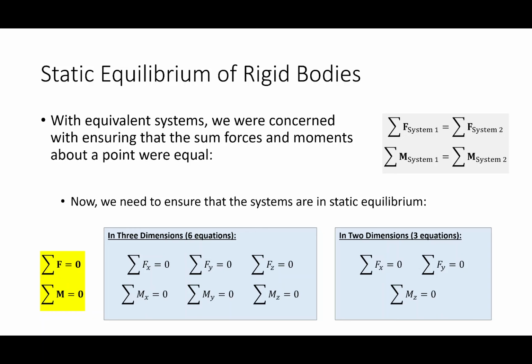In other words, in 2 dimensions, all we have are the sum of the forces in the x direction, the sum of forces in the y direction, and the sum of moments. That's all we have to deal with in 2D. And what's going to become evident today is that, if you were to treat problems arbitrarily, every single static equilibrium problem would be a 3x3 system of equations. But we can be crafty and choosy in regards to how we solve a problem to make the math very, very easy.